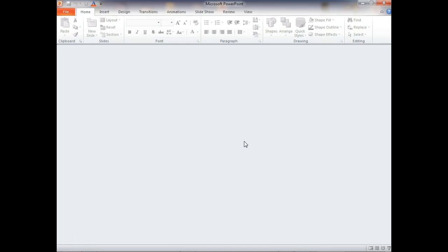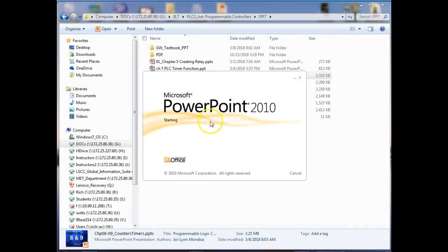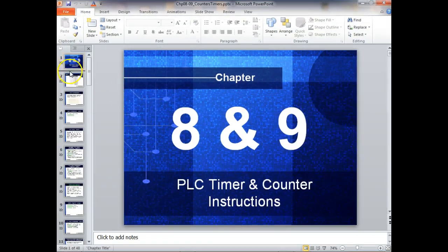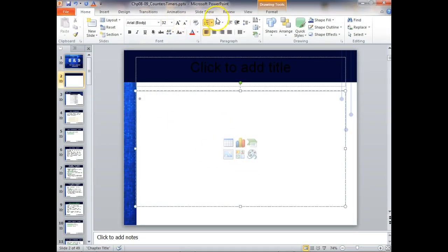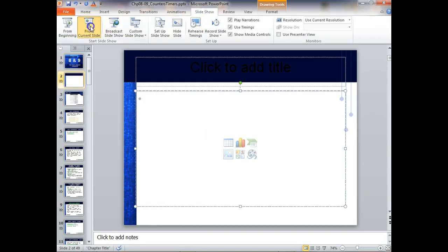So on our addressing, we have to specify what? First of all, we specify the type of instruction, right? Input or output. And then we have to specify what? The slot number. And then the other one is optional. So how does it go? Yeah, so what we would do, this would only apply if you got a multi-word module, right?